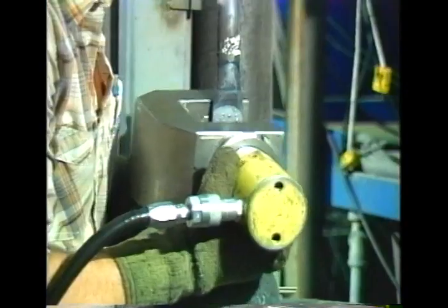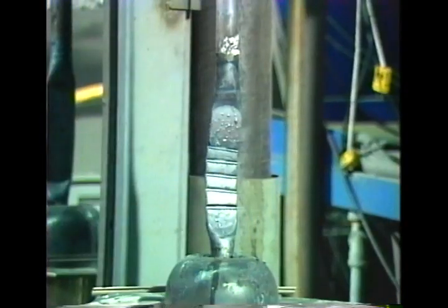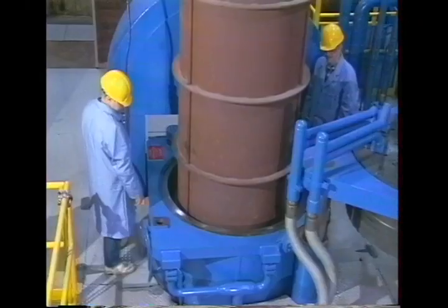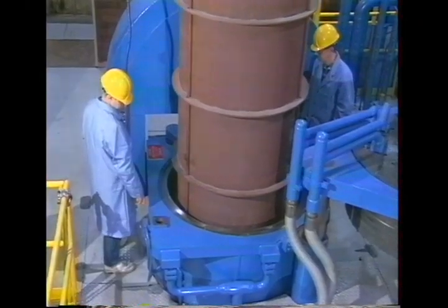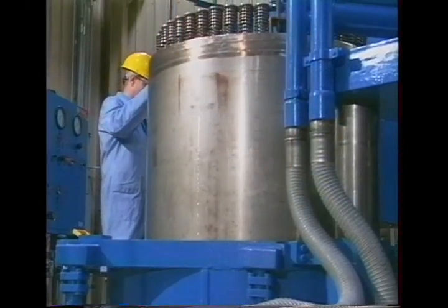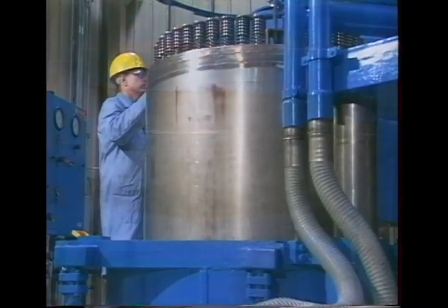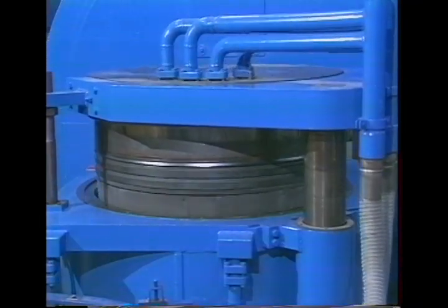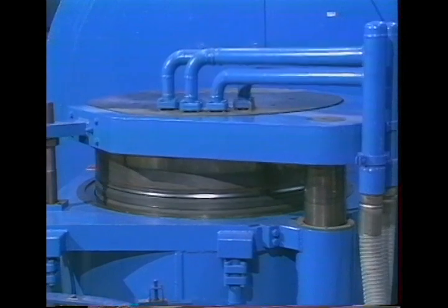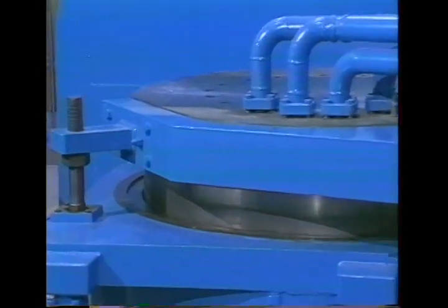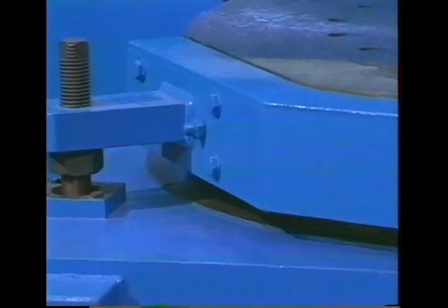Once filled, the molds are evacuated, sealed, and then assembled into fixture cans, which are lowered into the pressure vessel. The furnace is placed over the vessel, completely surrounding the molds, and sealed. Heat and gaseous pressure are then applied, consolidating and sintering the powder in a controlled atmosphere.